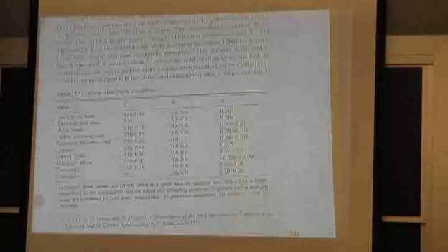Where did I lose my sheet from Hosford that gave me my R values? Here it is. Okay. Here's my sheet from Hosford with R values. For low carbon steel, I can get from 1.4 to 2.0. Well, 2.0 is my limit for a 110 texture, okay, in theory.